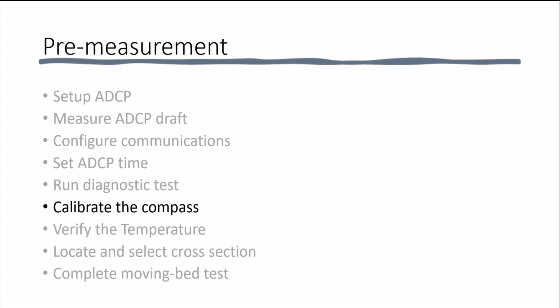Calibrate the compass. This is particularly important if you're using GPS or you're going to use a loop moving bed test. The methods to calibrate the compass for each of the instruments will be discussed in a separate video.